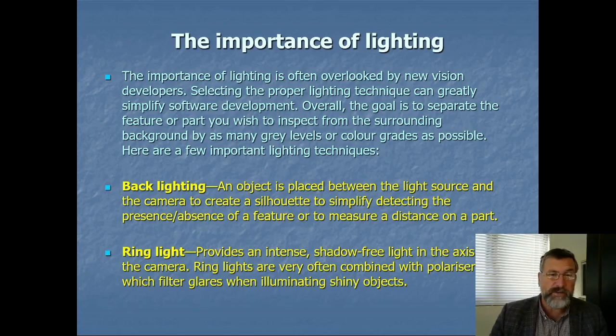Now, it's a similar kind of idea with removing glare using polarization. So what we've got there is, say, cellophane wrapping on an object. When the light's reflected off that, a reflection from a non-conductor tends to polarize the light. So the light being reflected will have a certain polarization. By putting a polarizing filter on the camera, you can adjust it so as to minimize that particular reflected light. So then you stand a better chance of reading the barcode underneath. There are other ways of doing it, but that's a couple of examples there, really.